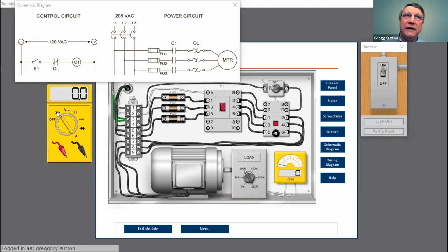You see we have three-phase, but what is it that's not working? Is it the three-phase power, or is your control circuit not working? Mm-hmm. Okay, so I would go from hot to neutral like you showed us. So I'm going to take the black one and I'm going to drag it over to this white guy for the neutral, and then take this red guy over to this hot. Should be here. Okay, okay. So we have found that we do have power coming in, but maybe it's not getting to the coil, right?